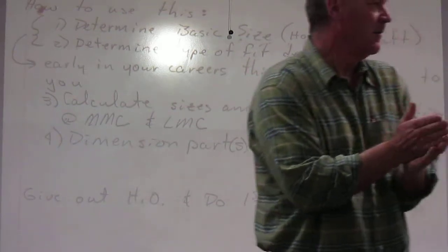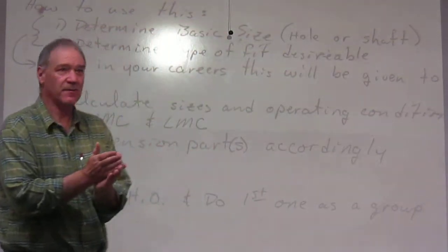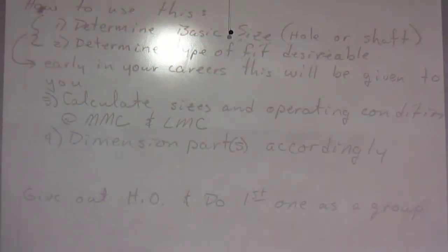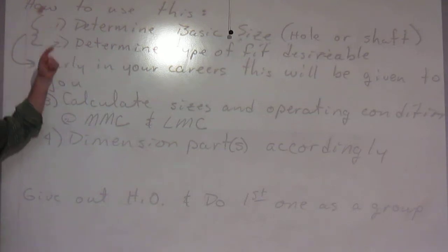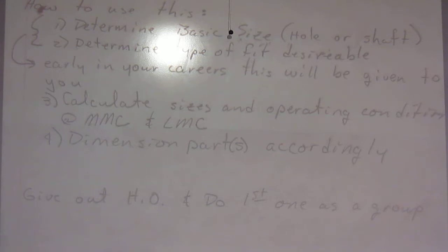Okay? Now, once we determine what the basic size is, or what we're driving everything with, and this can, by the way, be determined many different ways. Depends on how much torque we're running, what we're trying to drive. That's going to determine size, right? Next thing we're going to do is determine the type of fit. I put a note on here, early in your careers this is given to you, and it most certainly is. But once you get a little experience, you might make these calls.